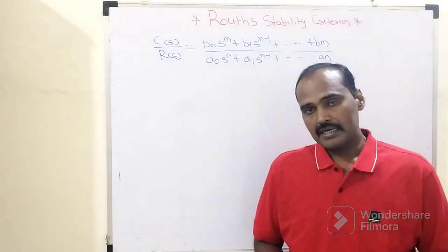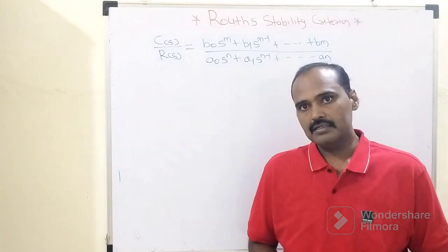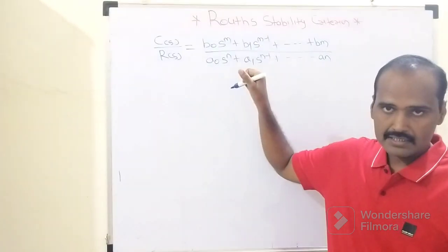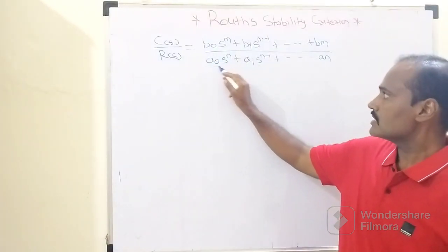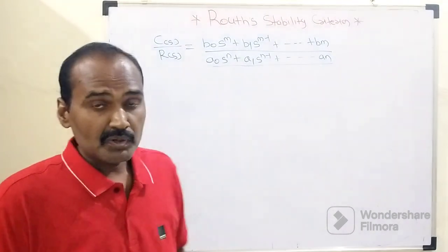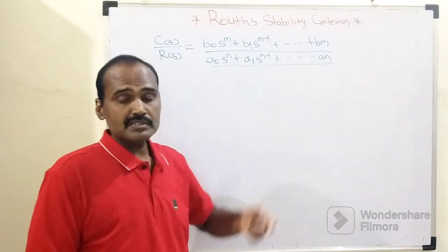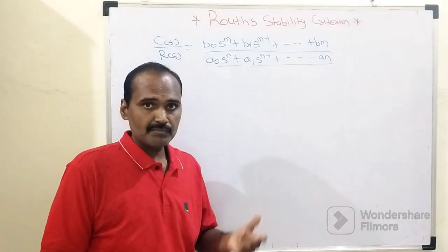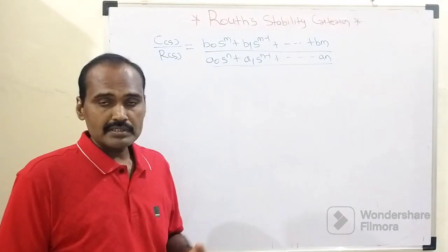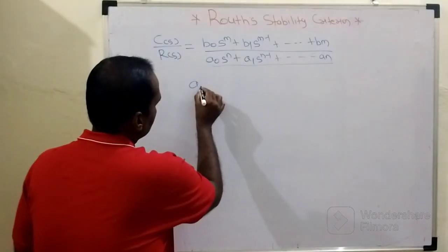So in order to start our journey towards the Routh stability criteria, first of all we need to understand that, similar to the Hurwitz criteria, we have such a type of transfer function, right? When the denominator of this transfer function is equated to 0, this entire term is called the characteristic equation, because whether it is the Hurwitz criteria or the Routh stability criteria, the characteristic equation plays a very important role in these two stability criteria in order to determine the overall stability of the control system.